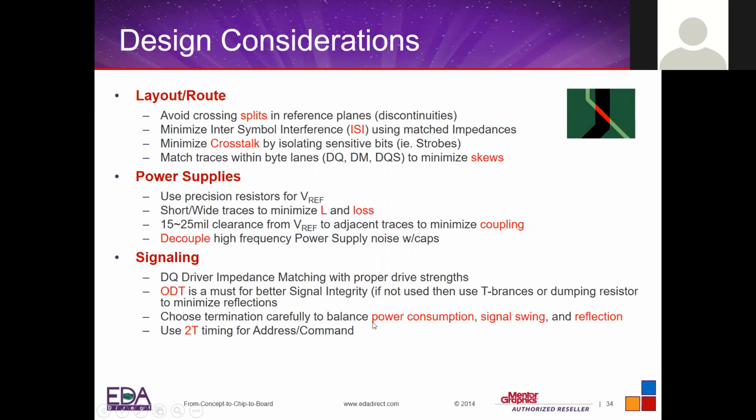Okay, and sometimes in your design, even though the product is working, you may have a criteria to save power. For example, it might be a portable device, it might be an IoT device, it might be a Bluetooth headphone, whatever the case might be. If you need to save power, you need to look at the signaling. Because sometimes your address line might be ringing, and those ringing, even though it's within the voltage limits for highs and lows, those ringing will consume active power. And by running simulation and seeing those and terminating those properly, you actually save power.